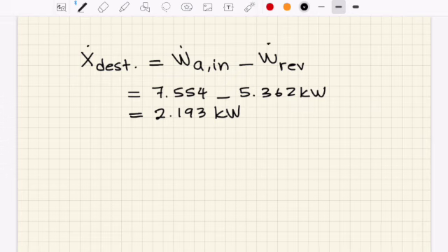We can also realize a certain thing here. The isentropic power input and the reversible power input seem to have two different values, because isentropic efficiency also considers adiabatic conditions, adiabatic together with reversible, so there is a slight difference.